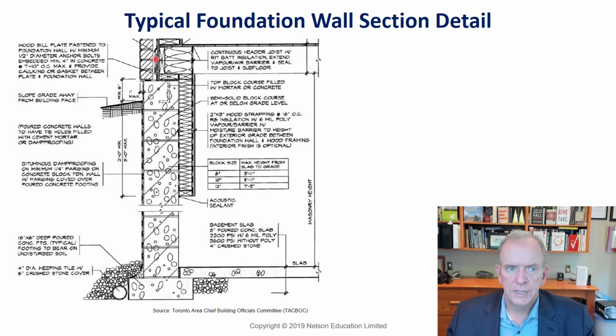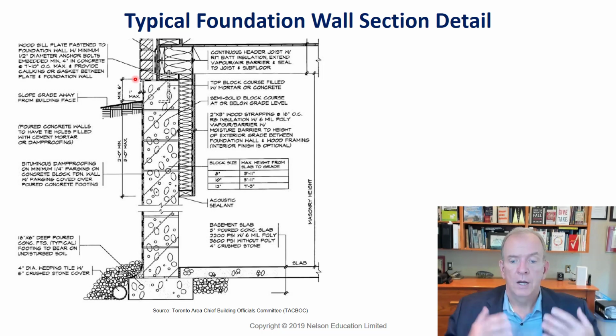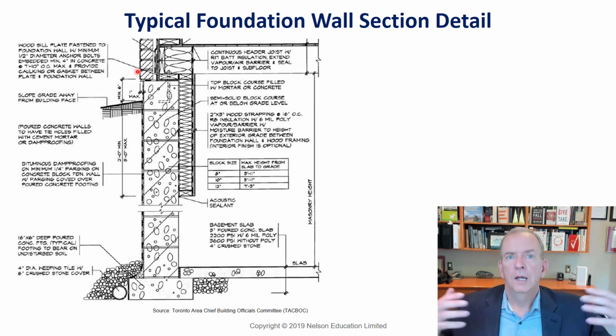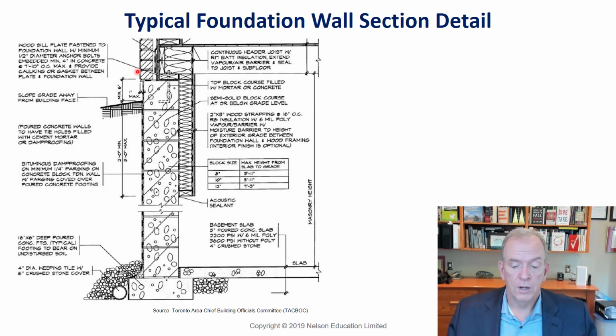Brick veneer on residential construction is non-structural. It does not carry the weight of the house. The weight of the house is supported by the framing members, not the brick. Older houses in Toronto, and older cities, are typically solid masonry. So that usually means it's block and it's brick. In that case, they are structural. The wall is usually like 8 to 10 inches thick. But a 4-inch or a 3-inch thick brick wall is not going to be a structural wall unto itself. It's more to protect against the weather, protect against lateral wind loads, and it looks nice and it lasts a long, long time.